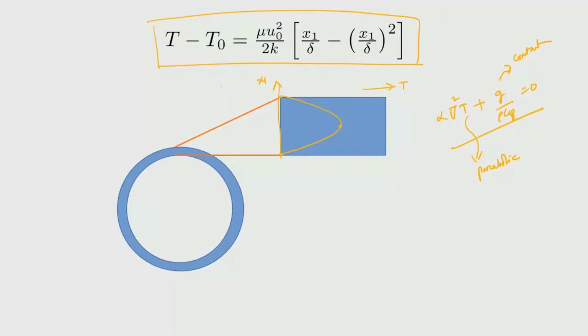Now, you could see that this problem can be solved with different boundary conditions, such as there being no heat flow across one of the walls, for example. What would then happen is the parabola will get shifted up. If one of the walls is insulating, then you may have a temperature profile which is still parabolic, but having its maximum on the surface, because then the slope of the temperature profile is 0, and that would accommodate. So, like this you could look at the solutions for various boundary conditions. This is one way by which the fluid flow is affecting the temperature profile.